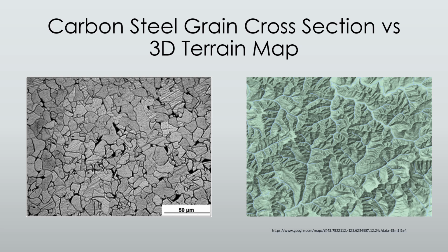There are many cathodes and anodes that are allowing charge transfer to occur because of the inherent grain structure present in metal. If you can look on the left, that's the flat, but on the right, if you were just to look at it almost as a bar graph of potential energy levels, that's really what's occurring on the surface of the metal.